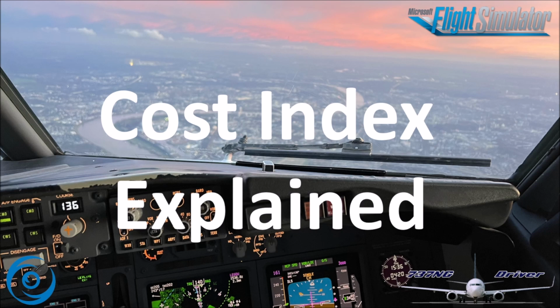And now, if we have a look at some typical cost indexes used on Boeing 757s of around 70, then we end up with speeds of 312 knots and Mach 0.794, and in the descent Mach 0.8 and on conversion 313 knots. So what we can see here is that in climb and cruise, a typical cost index is normally giving you a speed closer to the cost index 0 than the maximum cost index, while in the descent it can actually have a great influence if you just have a slight increase in your cost index.